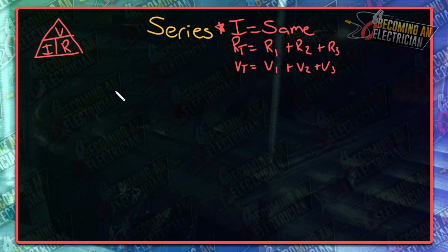But when you're first getting started up your teacher and in your schooling, you're going to learn about series circuits, typically DC electronic circuits like 5 volts, and learning about batteries and polarity and positive and negative. We're just going to keep things really simple. Again, the biggest thing that you need to know is current is always the same, and that's going to allow you to test your answers.